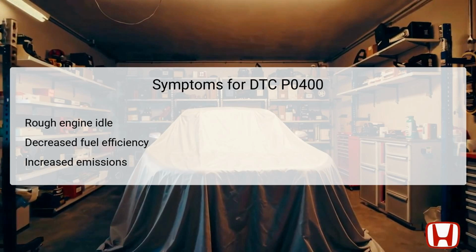Drivers may also experience decreased fuel efficiency as the engine compensates for the disrupted air-fuel ratio caused by EGR system failure. Another critical symptom is an increase in emissions, with the possibility of the vehicle failing emissions tests due to elevated nitrogen oxide levels.